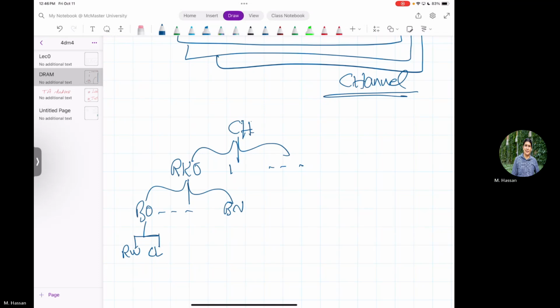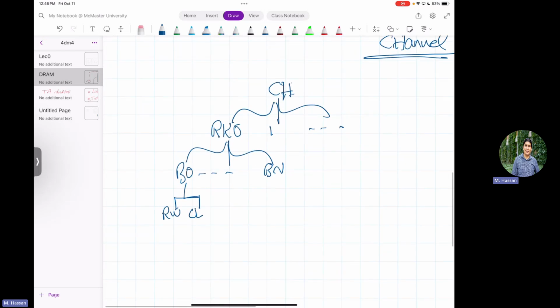Okay. So the terminology DRAM channel, in fact, is a very confusing terminology, both in industry and academia. The reason is sometimes people say a DRAM channel and they mean different things. The easiest, and I found the most convincing, is you define a channel as something that is completely independent. How do you say it's completely independent? It has its own separate memory controller on the chip. And most modern SoCs, in fact, have more than one memory controller.